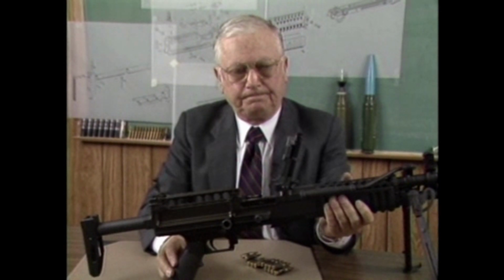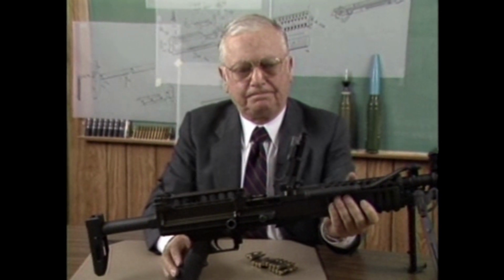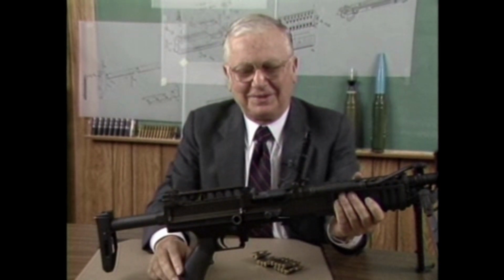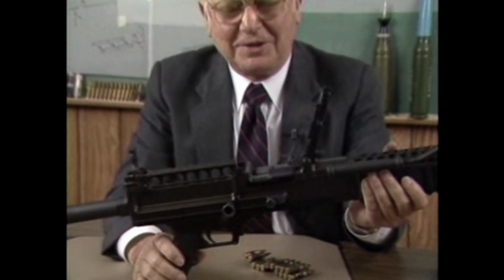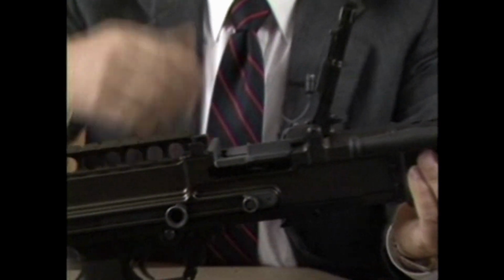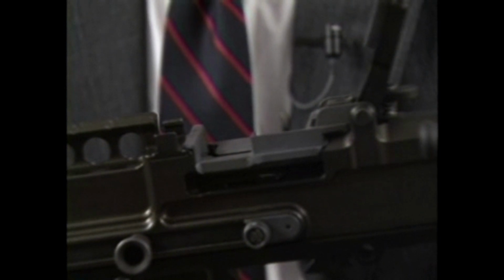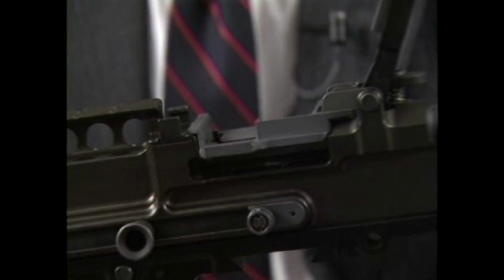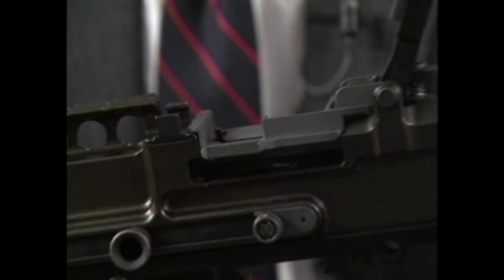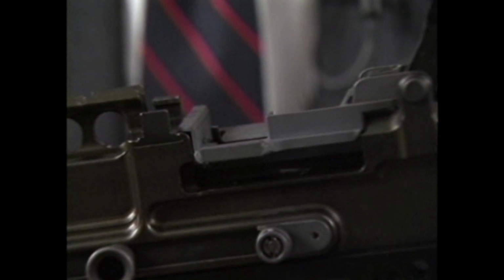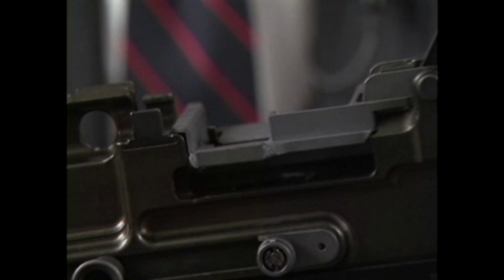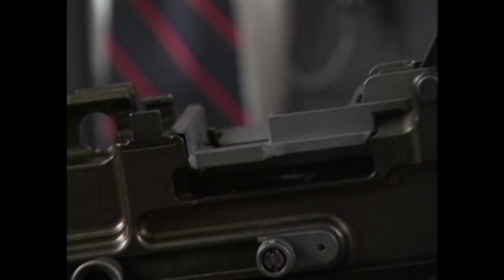Why is there the little lip on the end of the feed exit chute there? That little lip was an addition to deflect the links up so they didn't interfere with the ejected cases coming out. That was a problem we ran into that only happened about once every 100 rounds. There might be a hit or a near hit, cause some problems, and this deflects it just enough to where the problem doesn't exist anymore. One of those worrisome little things that you run into on any design.